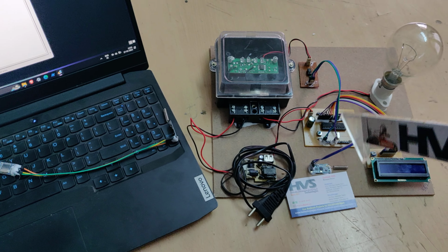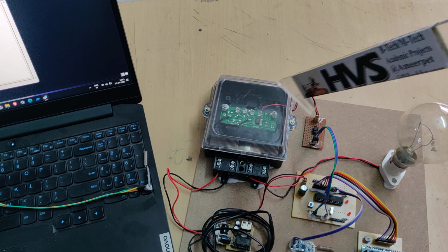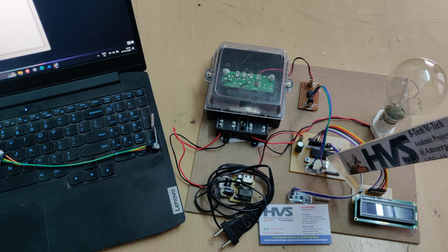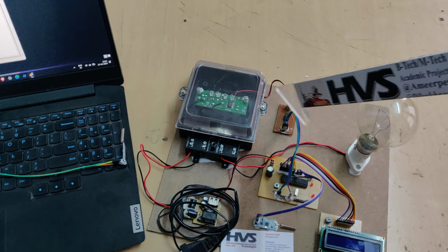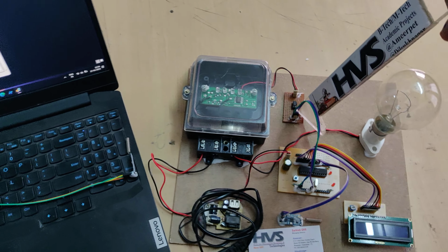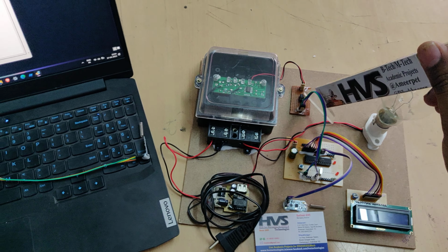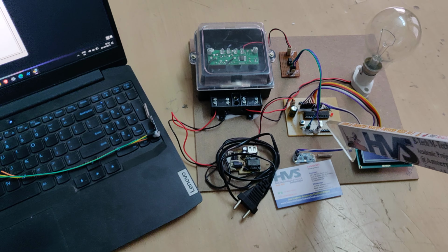So in order to prevent that damage, we place the optocoupler as a mediator between the LED and the PIC microcontroller. So if any short circuit occurs inside that, only this optocoupler PC817 will get damaged. So we can easily replace the small IC. So we have interfaced that pulse input to the A4 pin of our microcontroller.